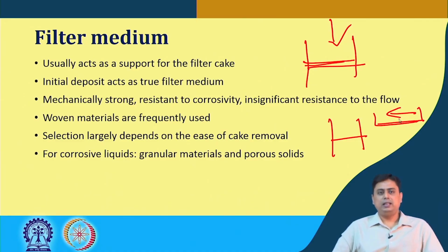Typical materials that are used for this filtering medium are the woven materials. Now, the selection of these woven materials largely depends on how easily the cake can be removed from the surface, because remember, in all these cases that we are discussing, we consider that solid particles are the valuable product that are deposited on the surface, and we can easily scrape it out.